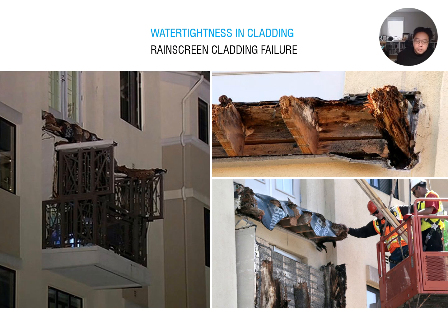So therefore, we talked about how we protect water from the cladding system, how we design the labyrinth design, how we design the PEC system, and why and how it works. And also, we have to provide the rain screen system. A rain screen system gives cavity space between the cladding and the fiberglass mesh sheeting, providing 1-inch, 2-inch spacing for ventilating air to dry out all the moisture and water. So please keep in mind this is an important design consideration, but also our safety from your assemblage.